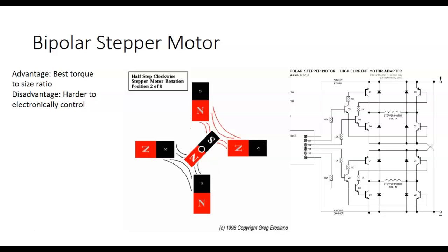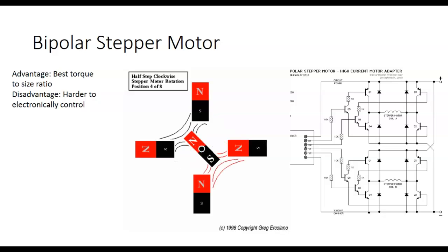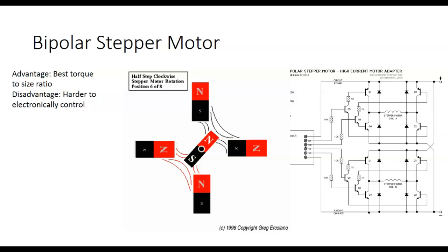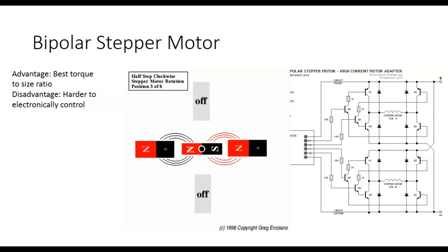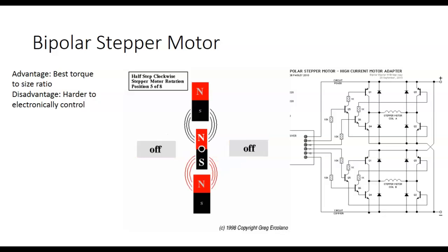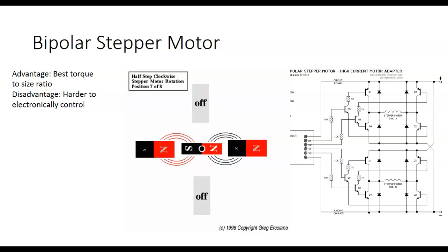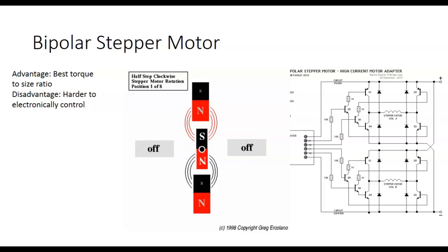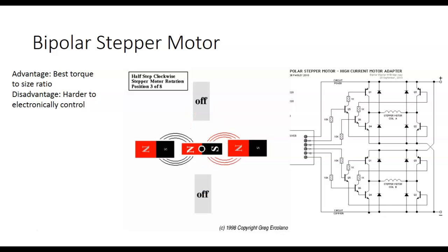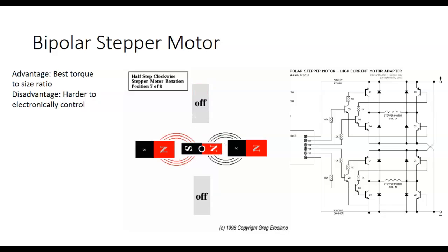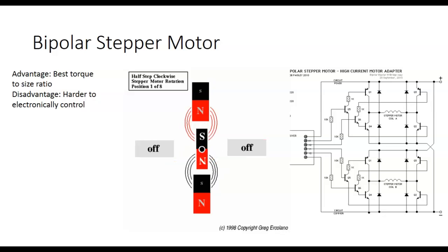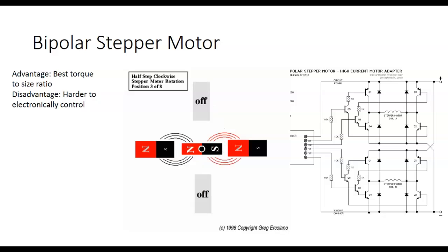We can run these open loop. All we got to do is find a home position, and then once we find a home position, we can control the position of the motor with steps. And I showed y'all how that thing finds its home position, right? It uses that inductive sensor, so it finds its home position. So we can literally stop that thing anywhere.